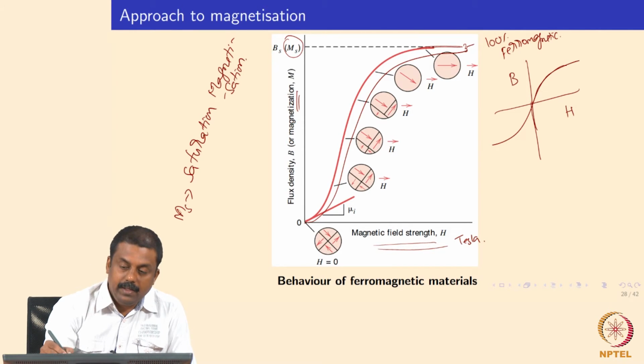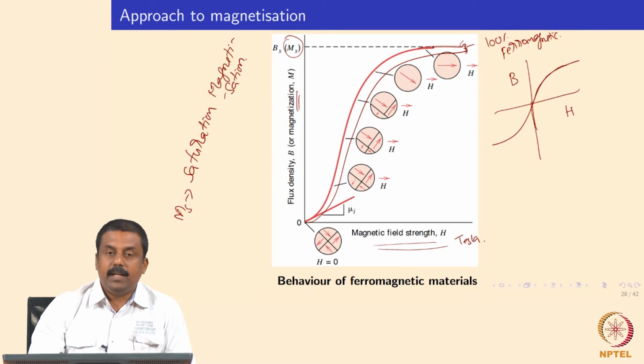The difference between the saturation value of the 100% ferromagnetic structure and that with paramagnetic constituents can give us quantitatively how much paramagnetic component is in the microstructure. So by measuring the saturation magnetization value with and without the paramagnetic component, we can quantify the retained austenite concentration, which is paramagnetic, in the microstructure.